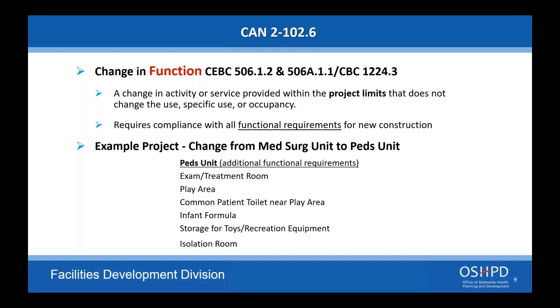If you're going to do a zero construction project, a lot of people aren't used to that, including our teams. We don't see a lot of them, but they have come through. So I would definitely recommend scheduling a meeting and talking through the process to make sure you're thinking this is going to be a zero cost, but yet all of a sudden you do have these actual triggers that do require some upgrades, something you might not have thought of before, such as converting patient rooms to offices. Now you have to do things with the doors or the egress or the corridors. So you have to be really careful about that, and I would definitely meet with us prior to doing that.